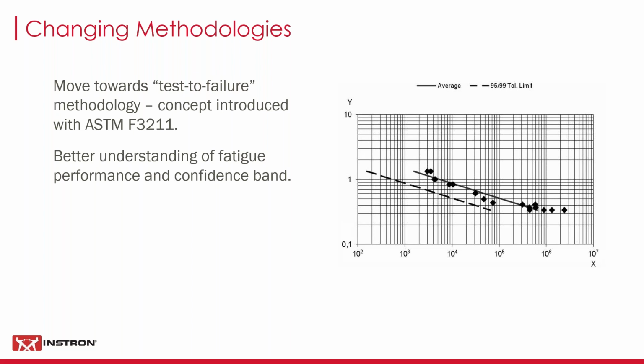It's not like testing a simple bar of metal where, when you get to the end of the fatigue limit, it's in two pieces. When we're talking about a structure like a stent, then there are different things that could happen. And actually, that's a good point, because if you don't stop and inspect immediately, then by continuing to cycle you could overlap, you could lose that indication of what the initial failure was.